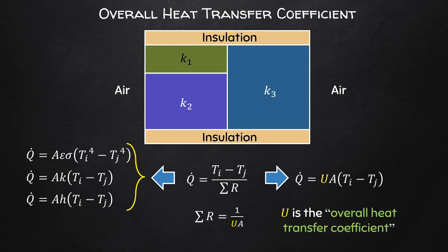Now, the overall heat transfer coefficient is useful to us as it can actually be determined experimentally. We run two fluids past each other through heat exchange equipment, and we determine how effective the heat transfer is. And we can therefore determine what the overall heat transfer coefficient is. We run a few tests at different flow rates, etc. We will get into the design of heat exchangers shortly, but it can be determined without knowing actual properties or thermal boundary layers, gap resistances, or fouling for that matter.